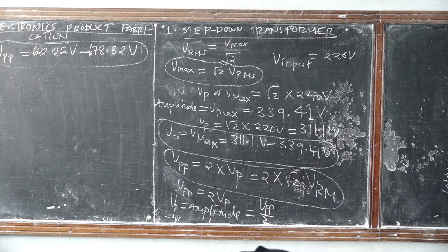Because in signal generators, we don't have a space to fit the root mean square voltage. In most simulation software, when we choose the alternator to present the domestic power, we don't have a chance to change the root mean square voltage. We only have the chance to change the amplitude of that sinusoidal signal.